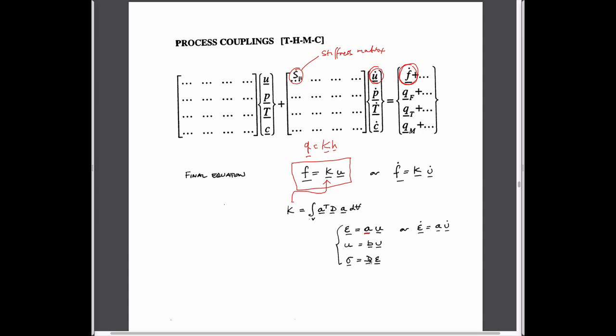And the constitutive matrix is Hooke's law. So this is Hooke's law, where before it was Darcy's law. So before it was v equal to hydraulic conductivity times dh/dx. But it's actually quite similar. This is a strain, but a strain, if we write it out in shorthand, is a change in displacement with location, as indeed this is a change in head as a function of location. So they're related to gradients of these properties. And so there is some commonality in this.